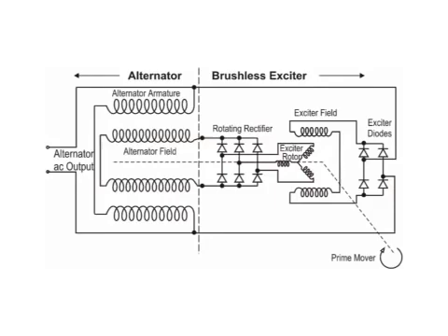Now that we've produced a voltage at our alternator output, and we have not yet connected load, we have to talk about a couple of things, and that is the voltage drops that occur internally on any machine, including in this case an alternator. Now, if we go back to our formulas, voltage is equal to current times resistance. Anytime we have zero current flow, that means we have 0 volt drop. So when no current is flowing, there are no internal volt drops.